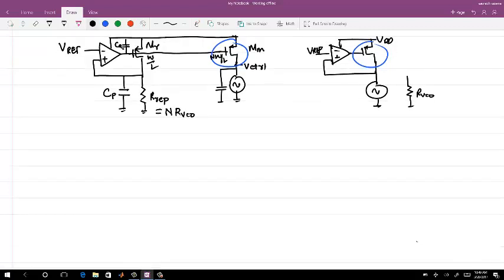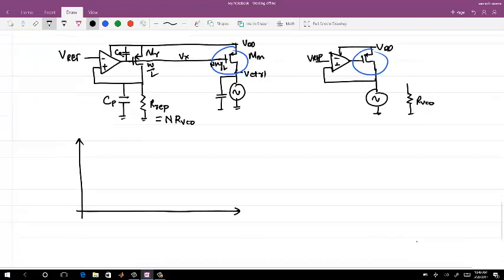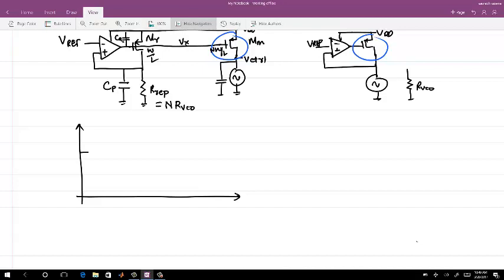So it will be easier for you to get, means you have to work out all this expression. So let me just say this node is Vx. So from VDD, you can get this as V out 1. So this is V out 1 by VDD. You can get this transfer function with the output pole as a dominant pole. The thing which you need to find is Vx by VDD, and then the V out transfer function.